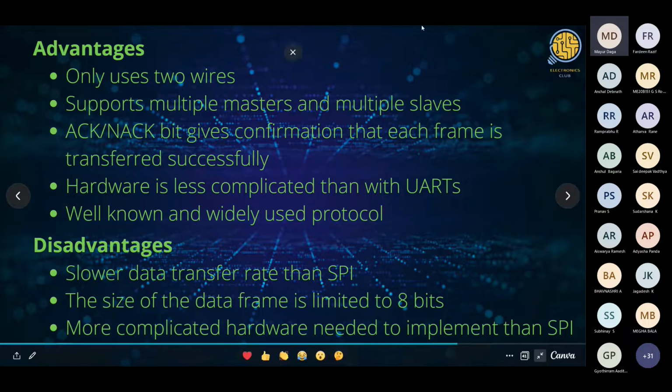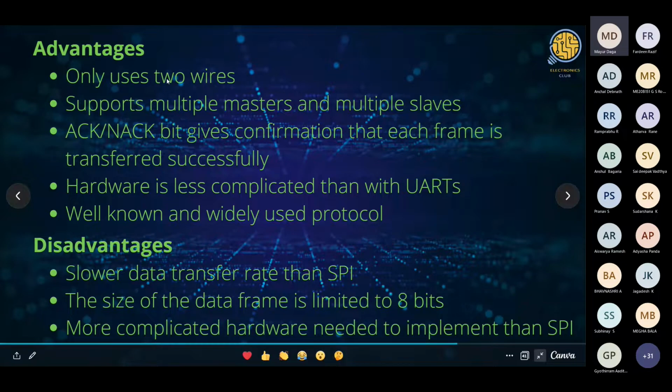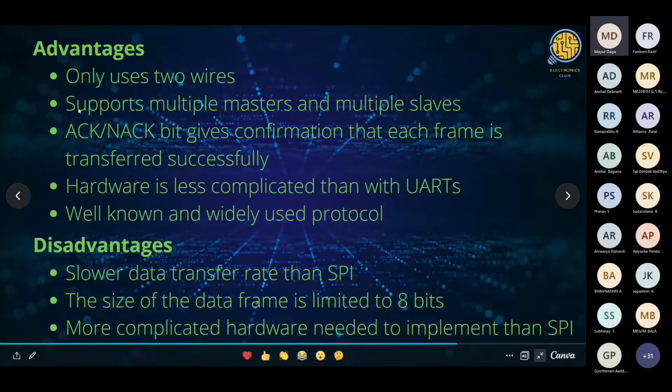This all has a common ground, and so I2C actually has three wires: one is SDA, one is SCL, and a common ground. It supports multiple masters and multiple slaves, unlike SPI.